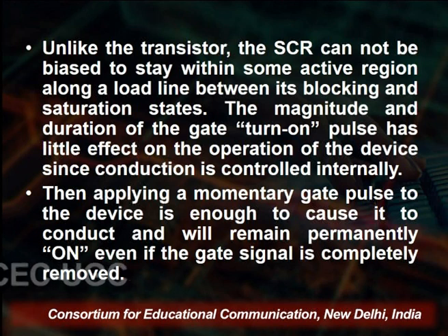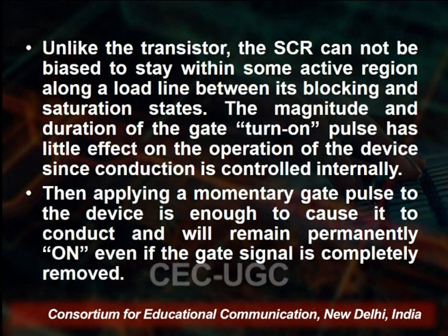So the magnitude and the duration of the gate turn-on pulse has little effect on the operation of the device, since the conduction is controlled initially. So applying a momentary gate pulse to the device is enough to cause it to conduct. When we give just a momentary gate pulse to the device, it conducts and will remain permanently in the on state even if the gate signal is completely removed. It means the gate signal is used to trigger the device.